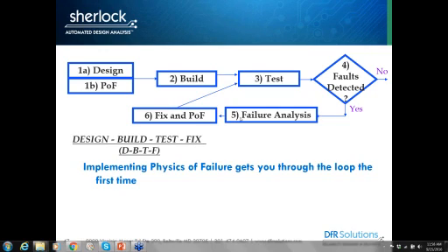I would say you want to run your Sherlock assessment before the printed circuit board build. Yes, you want to have it prior to the PCB build. Hold off on building the printed circuit boards until after the Sherlock assessment, to make sure that I don't have to change laminate materials or something like that.